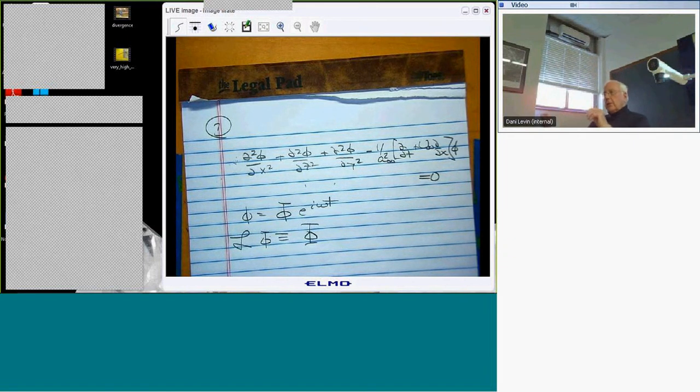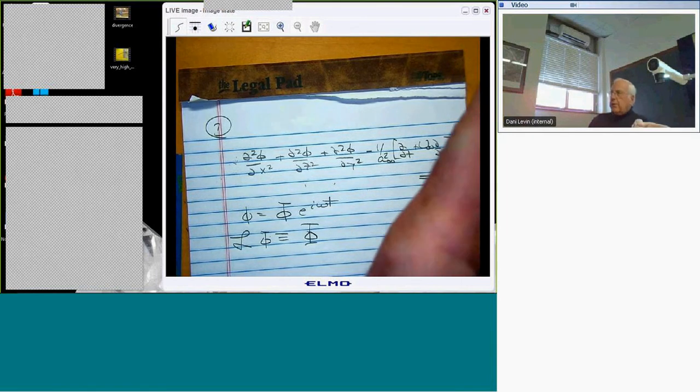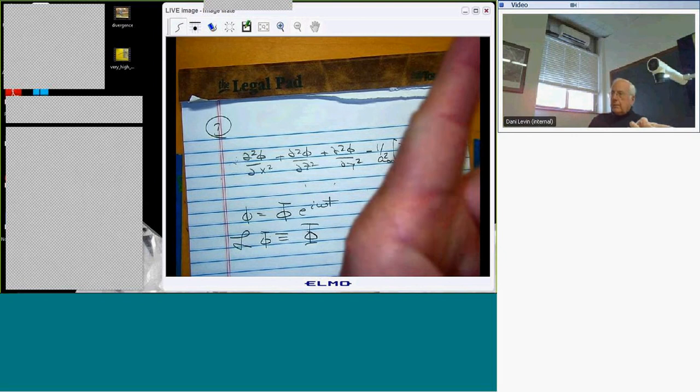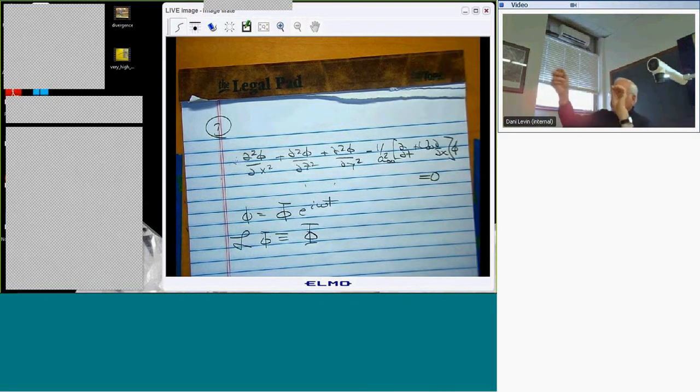The parts of the wing and the flow for y greater than 0 are interacting with the parts that are less than 0 and vice versa. So, unfortunately not. Sorry about that. When you do the numerics, you might be able to. That is, when you get down to that integral equation, you might be able to invoke symmetry then, right? So you might only need half as many boxes if you invoke symmetry. But you can't use Laplace transform. That's a step too far.